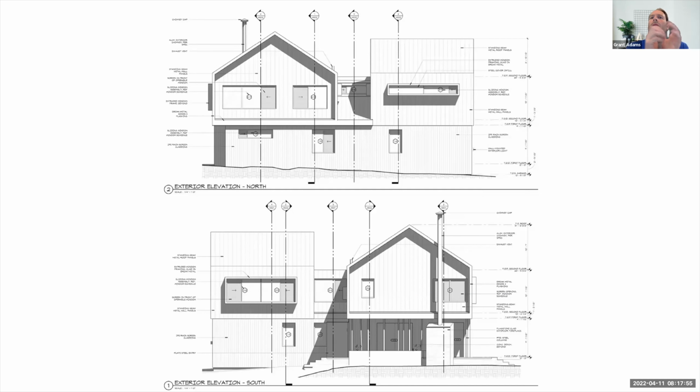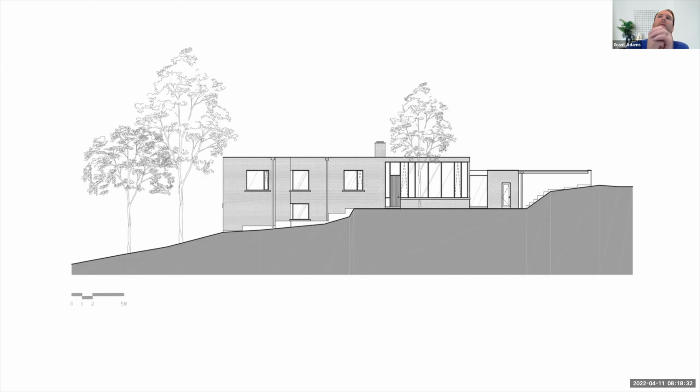So this is a little bit more technical. We've got some section cuts shown here. Those would be these lines up at the top. Those are, like I said, a little bit more technical. We've also got a bunch of dimensions and stuff on the sides. Those are nice and thin, elevations, etc., spot elevations. But the same rules apply here. The thickest lines are the ones at the ground level. And then the outline of the building and the things that are closest to us are the thickest. And we could go through and number those in the same kind of hierarchy level.